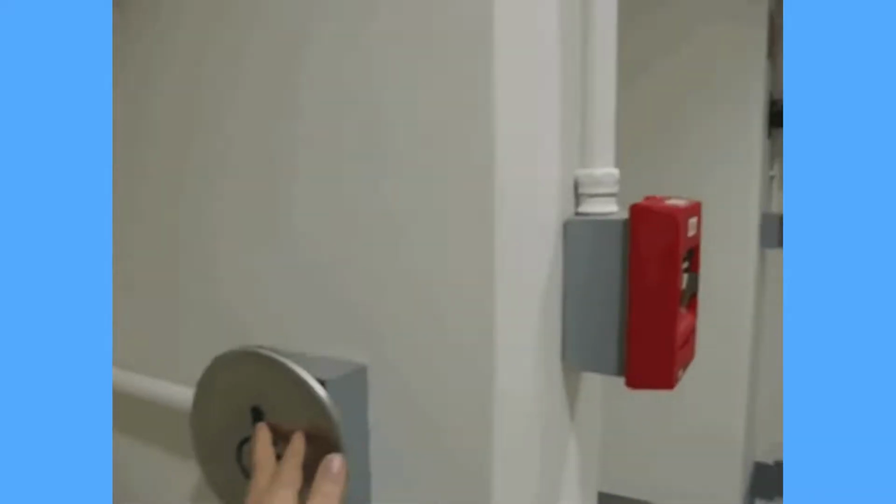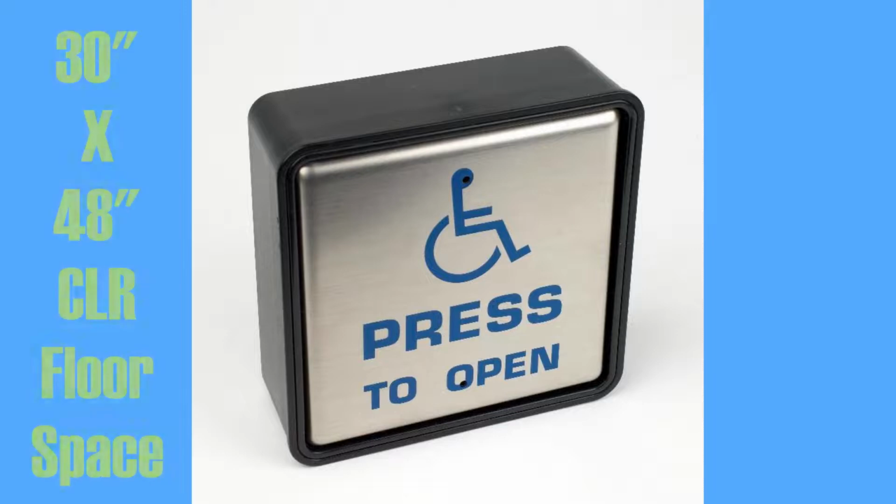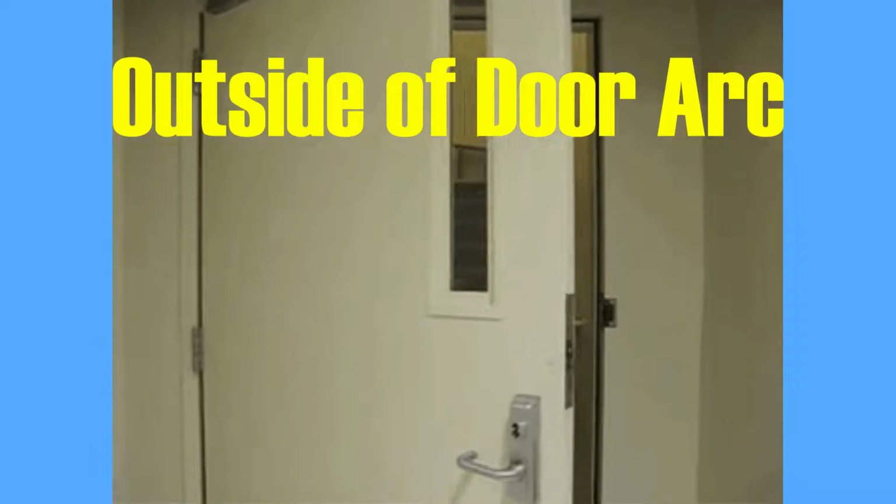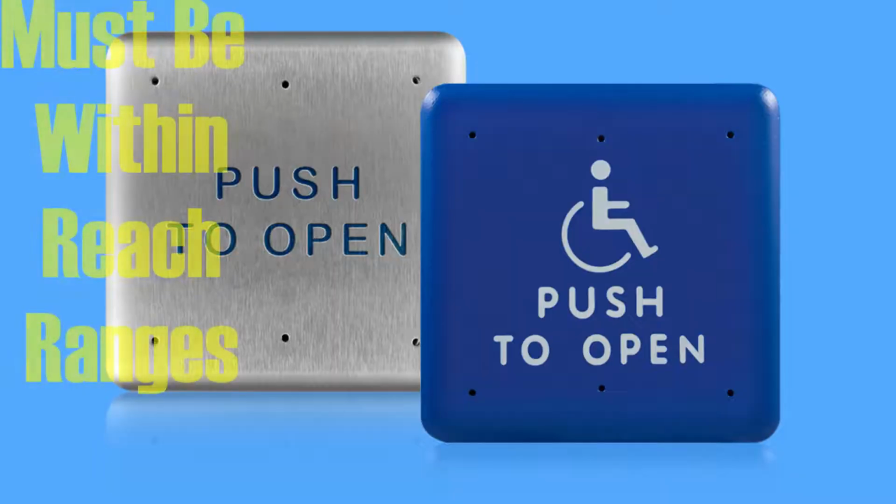Manually operated controls shall have a 30-inch by 48-inch clear floor space adjacent to the control. The clear floor space must be outside the arc of the door swing, and it must be located in one or more of the reach ranges.